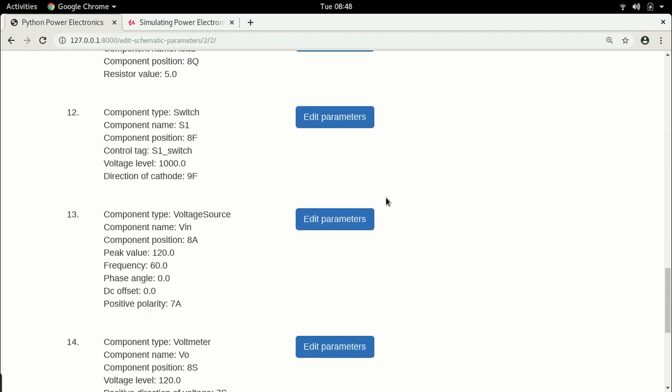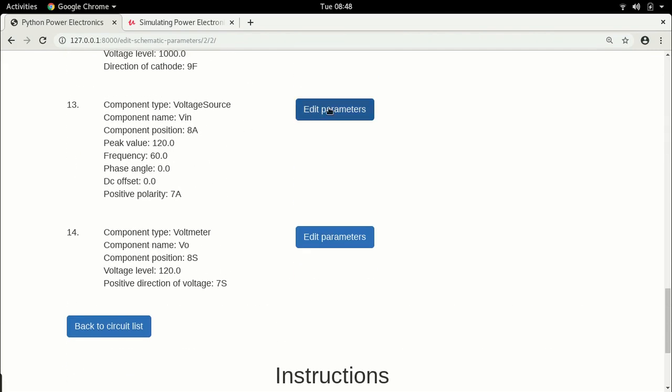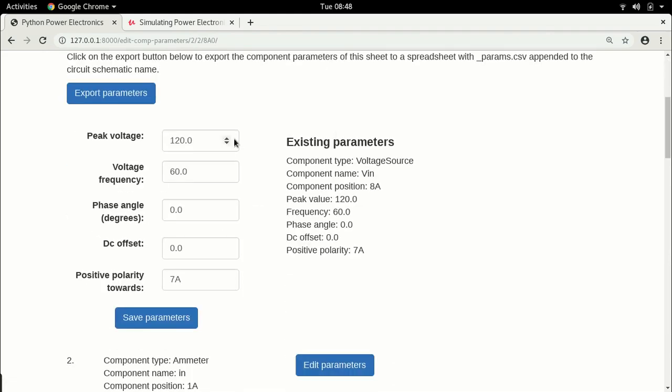And then there should be the last, which is the voltage source. The voltage source, as before, is a DC voltage. This is a DC converter, so we don't have any AC. So we can just set these to be 0. For the DC offset, let's make it a 12 volt DC source, which we want to step up to something higher. Alright, that is our objective.